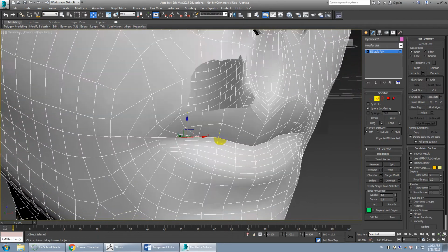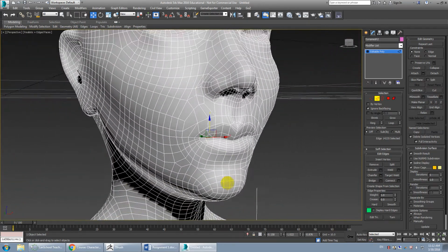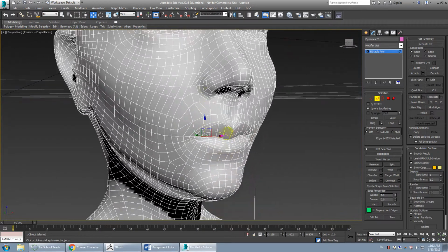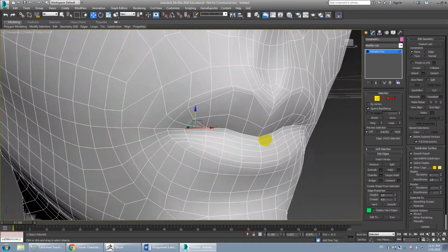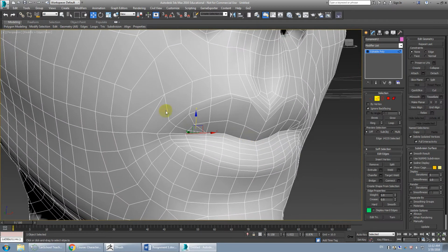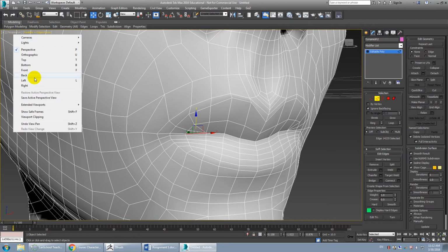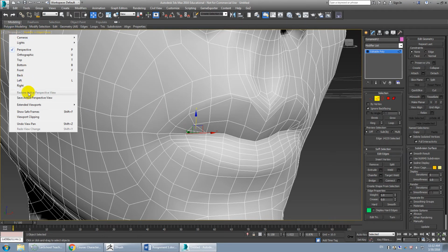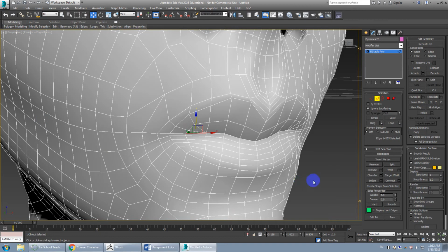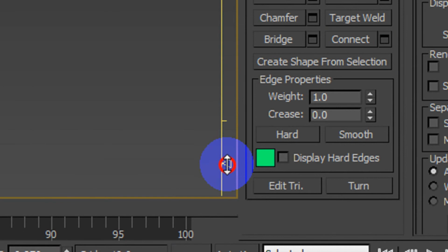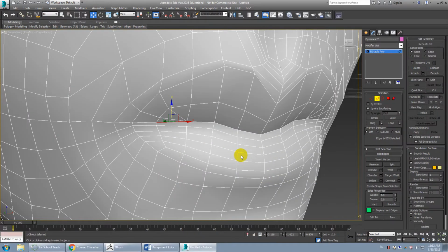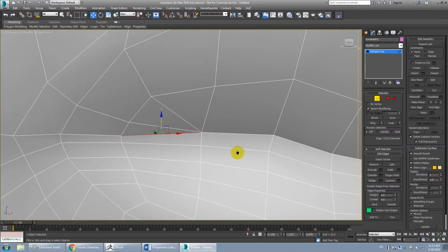One thing you may also encounter, this may happen in Max or Maya, you see when you have objects that are very small, like ZBrush's working scale is actually quite tiny, and so it's very difficult to zoom in. You'll want to look for this in Maya if you're working in Maya as well. It's got the same kind of label, set up a little bit differently, of course, but in Max you go to perspective and viewport clipping. This is basically the range at which the camera cuts off the visibility of an object. And the lower, it sort of puts this yellow bar on the side. And if I drop this lower notch down, I should be able to zoom in much, much closer to the object without it cutting off the mesh.